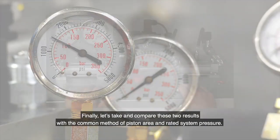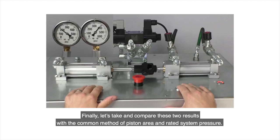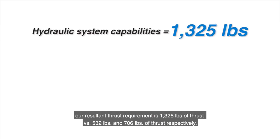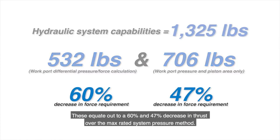You now see why measuring return line pressure and calculating force using the effective surface area is essential for accurately determining thrust. Finally, let's compare these two results with the common method of piston area and rated system pressure. Even assuming that the max system pressure is very close to what we measured, for example 750 psi, our resultant thrust requirement is 1,325 pounds of thrust versus 532 pounds and 706 pounds of thrust respectively. These equate to a 60% and 47% decrease in thrust over the max rated system pressure method.